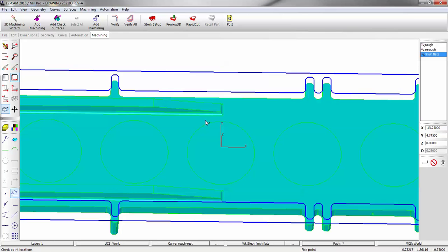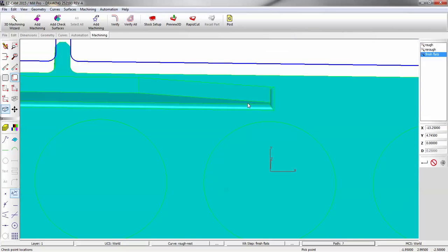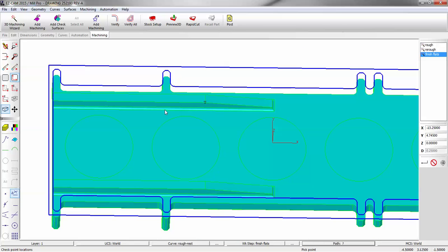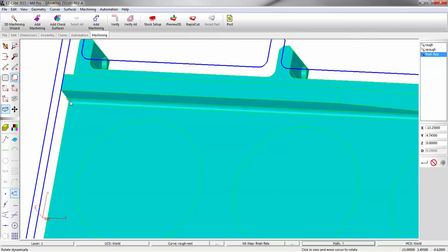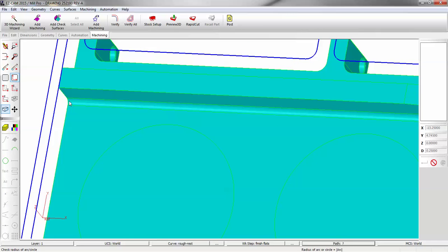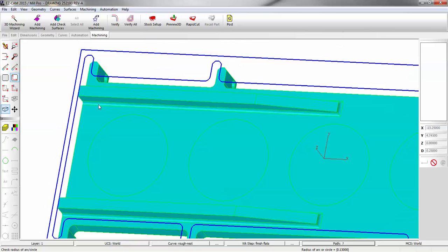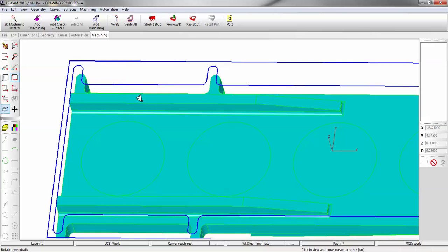Let's go in and measure. Maybe we'll use a bullnose tool. We could go back in and do a 3D machine on that. Let's just measure what that radius represents. So we can use a 1/4 inch cutter. We'll go back in and we'll use that as a secondary op.